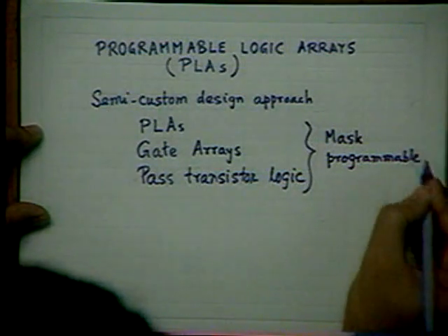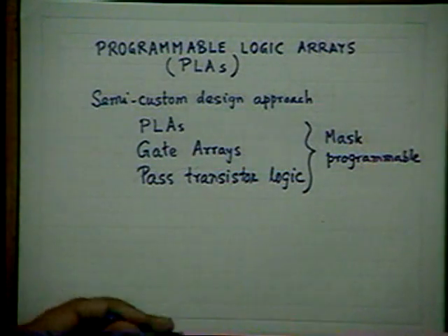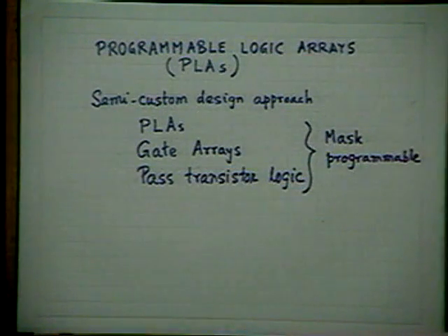That means the programmability is only in the manufacturing stage. The manufacturers can keep prefabricated slices with them, hundreds and thousands in stock. Then whatever order you place with them for the circuit, you can send your design for the contact hole patterns and the metallization pattern. And you can send the software, the data bank for that.